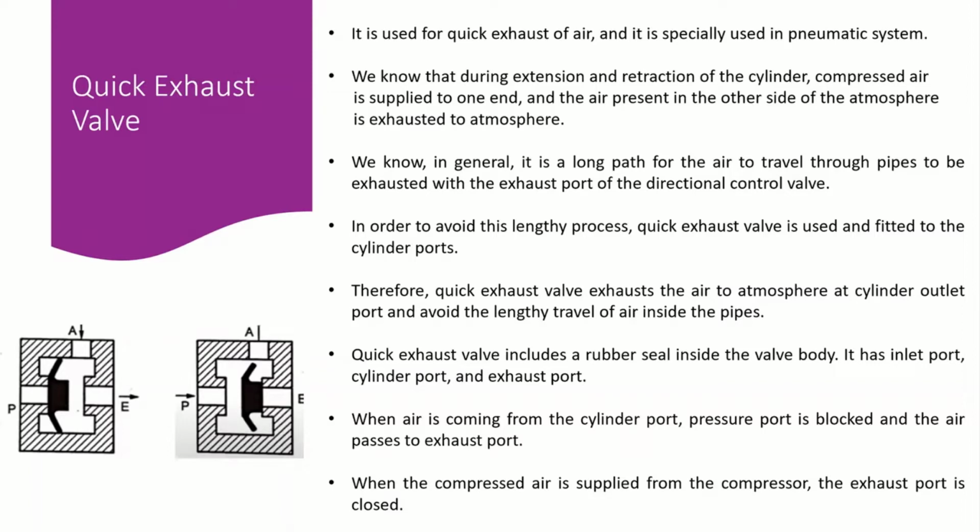In general it is a long path for the air to travel through pipes to be exhausted at the exhaust port of the directional valve. Depending on the length of the pipes, it can take a few seconds, even a minute, for the air to get to the directional control valve and be exhausted, right?